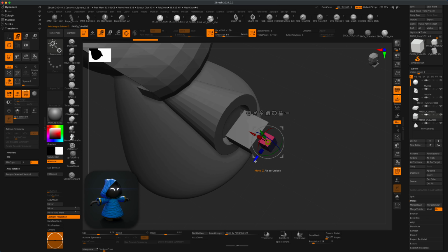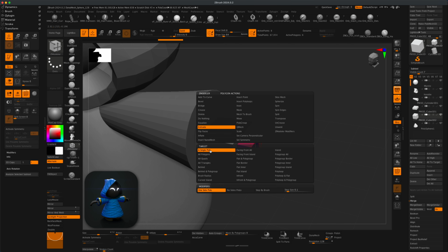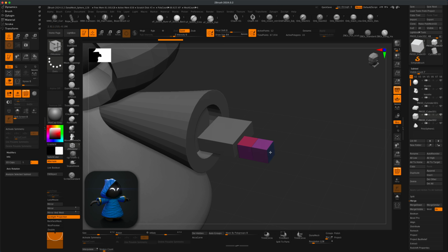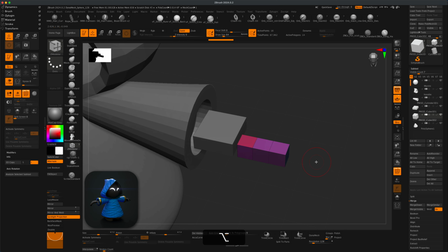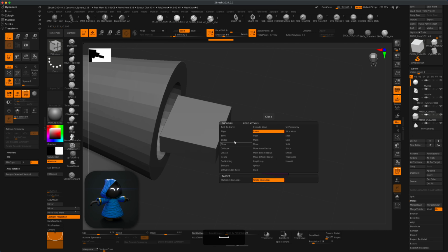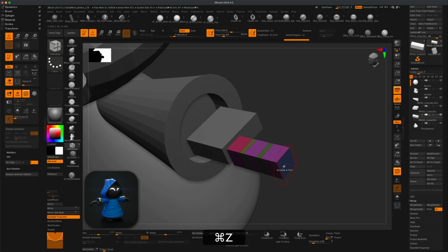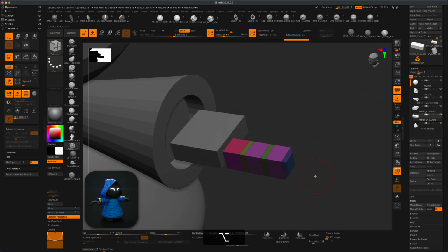So I'm going to go to this one first. Let's grab zModeler. I'm going to hover over my face, and if I go to extrude, it still says single poly. That's great. Let's just do something like this for one of the fingers, right? And if we wanted to add additional edges here, we could always bevel them, right? Let's go to bevel. Let's just do something like this, just so we can always bend our fingers, right? We can even bevel the ends, right? So that's gonna maybe look a little more like a finger.